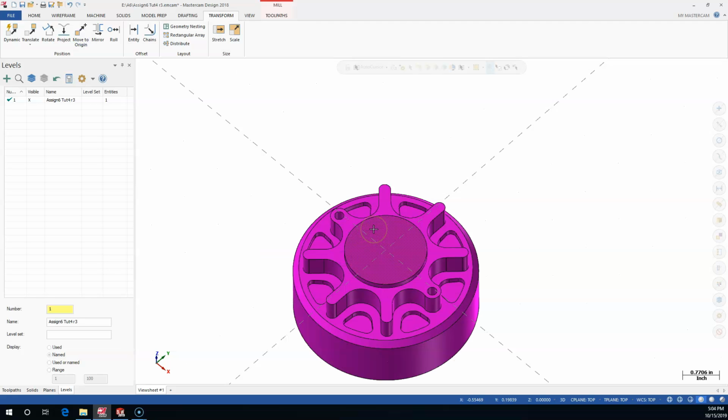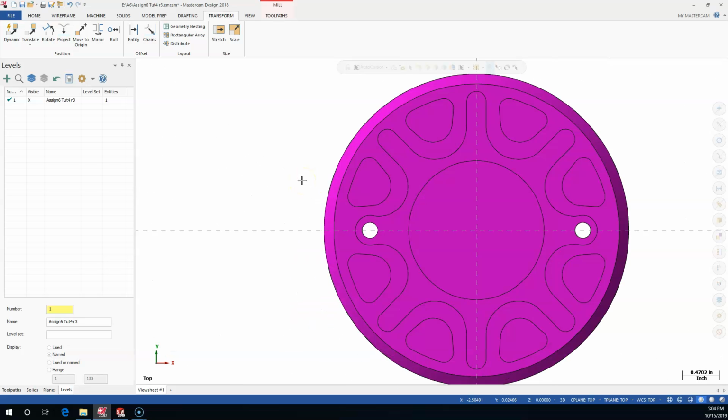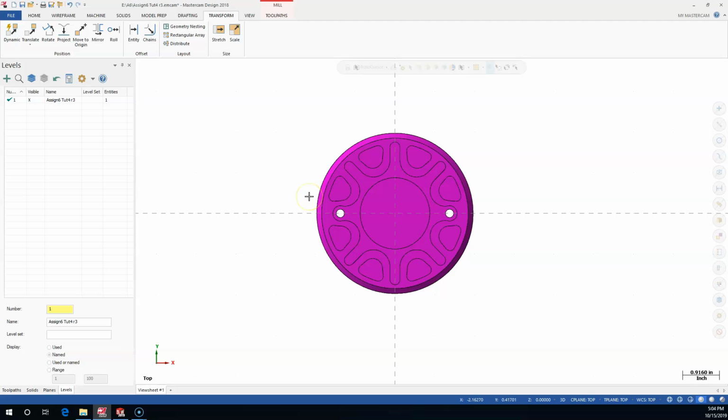All right, so very briefly, it popped up with that little green cross right at the center. I don't think I waited for that on the first time around. That puts me into position. And then if I want to draw the stock, now I can put stock in place, get it into position, and then pick the coordinate system.